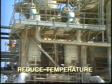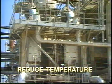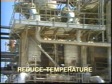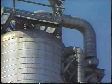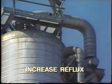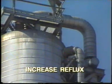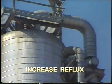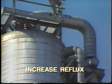Because butane requires more heat to vaporize than propane, reducing the heat input to the tower decreases the amount of butane going overhead. Another way to remove butane from the top product is to increase the amount of heat removed from the tower. We can do this by increasing the reflux rate. The downward flow of reflux condenses the heavier components in the upward flowing vapors. In this column, butane is the heavy component, so increasing the reflux rate results in a top product containing less butane.